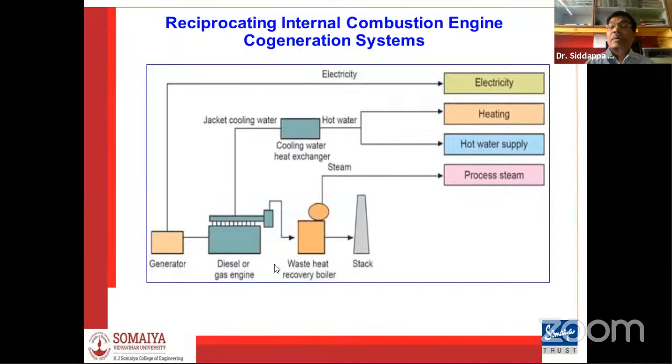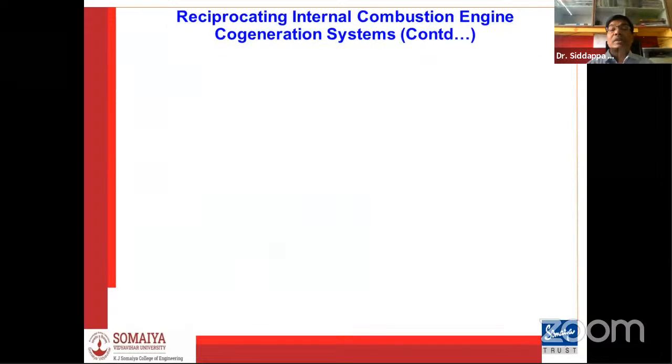A fraction of the heat liberated during the combustion process will be carried by the jacket water, because the combustion chamber goes on absorbing heat during combustion, so it is necessary to carry away the heat absorbed by the combustion chamber wall and keep the wall at a constant temperature.